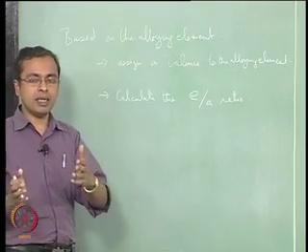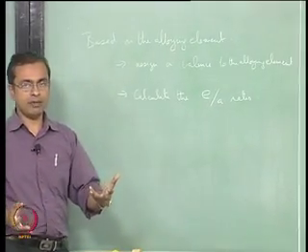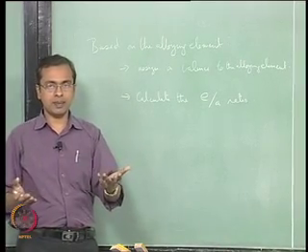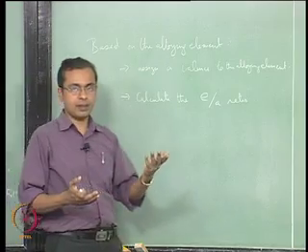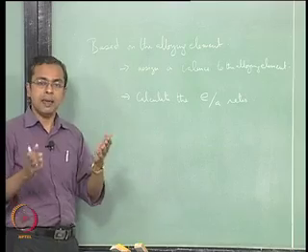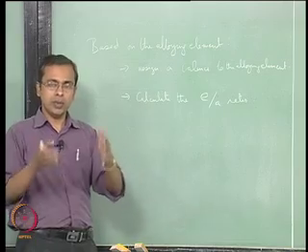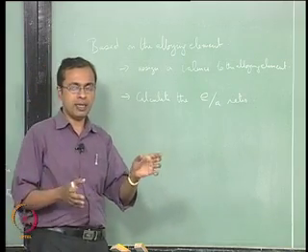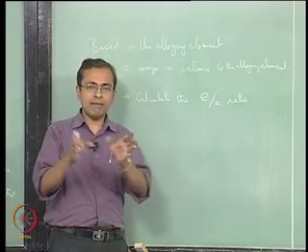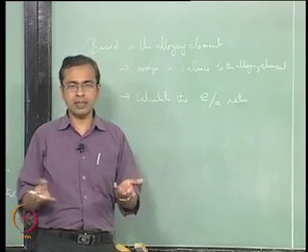Okay, so you have silver and it will have some valency, you are adding another alloying element which has a different valency. So you can take a weighted average of these two valencies based on the molar ratio of how you have added these two elements. Based on the molar ratio, you can take a weighted average of the valency of one atom versus the valency of the other atom. So you can get an average valency on a per atom basis. It is fairly straightforward that way.